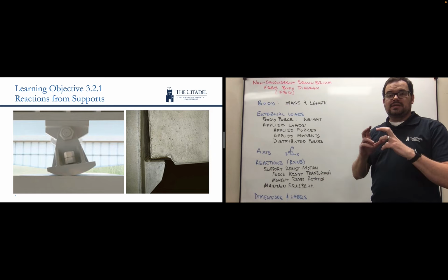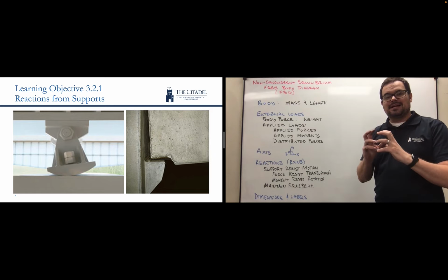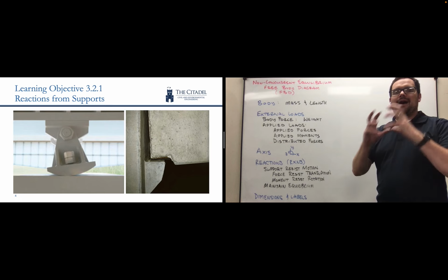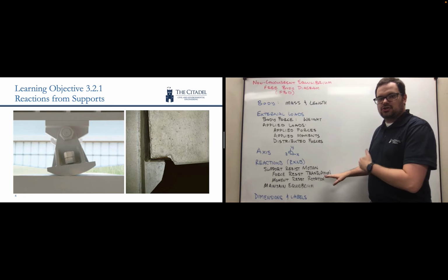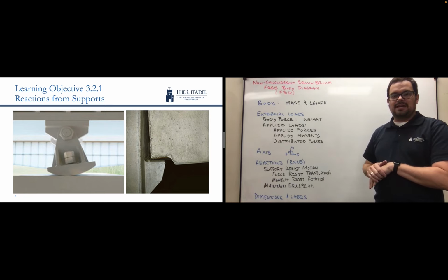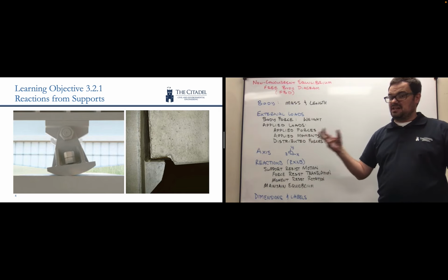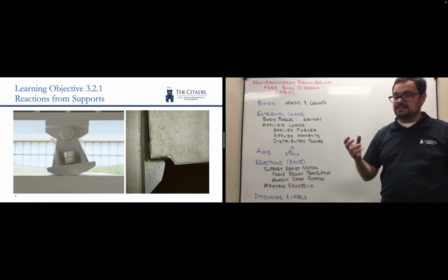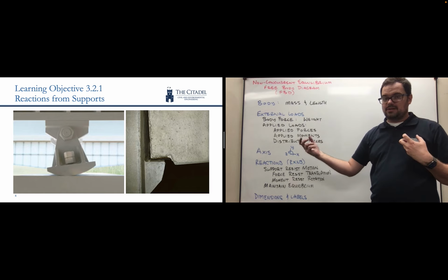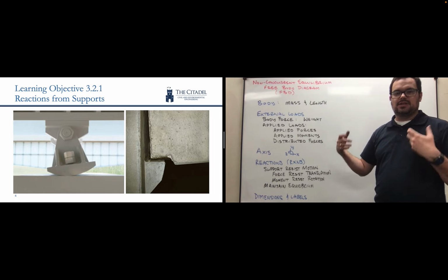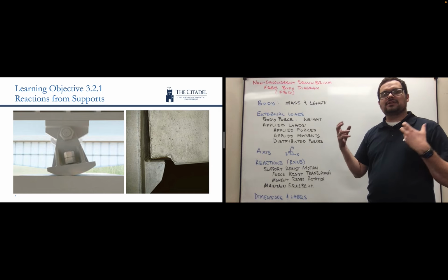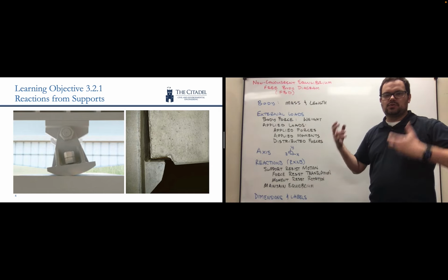When we look at a joint or a connection by itself, we're asking how this connection contributes to generating a reaction. It doesn't have to do everything, because most of the time a beam will touch the ground in multiple places, and those reactions together will make sure there's no translation and no rotation. But we want to ask which part this particular joint is doing.